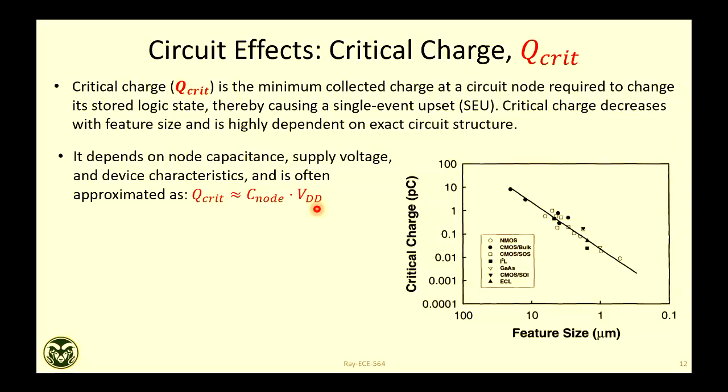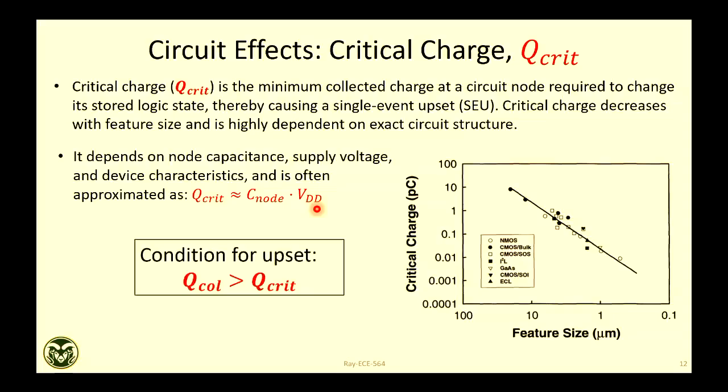So yeah, that's why this is a serious issue for ultra scaled devices. We are scaling, right? Scaling is the workhorse for the semiconductor industry. You are increasing the bit density, but you are making it more and more sensitive because your critical charge is going down. But the story is not simple, because what matters is your collected charge, right? It should be more than the critical charge.